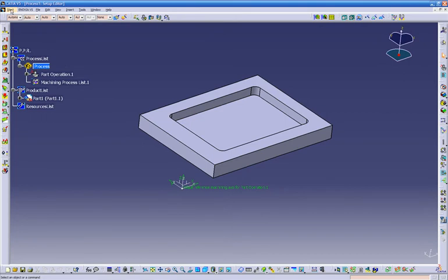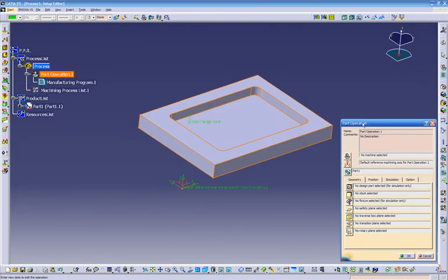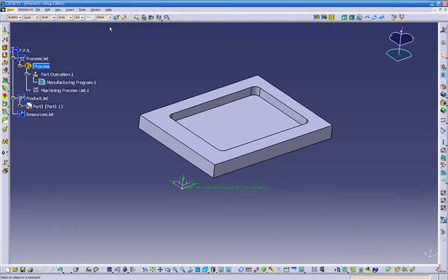So every time we start advanced machining, very first thing we have to set it up. So first thing is we double click on part operation and we get our part operation window. So every time we have to get familiar and used to that. We always have to do this. Before I do this, I'm gonna cancel this for a quick second because I want to create my plane and my boundary box, my stock material. So I'm just gonna cancel this for one quick second.